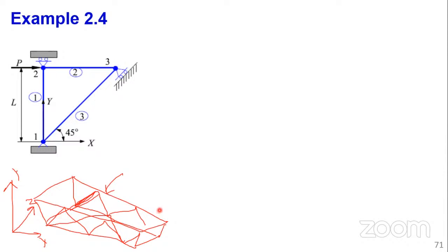It's just addition and reduction using the node boundary conditions. So if you don't define adequate boundary conditions, or if you over-constrain your structure and try to run your analysis, let's say in Abaqus, it throws an error, maybe telling you there are too many constraints. We are defining a boundary value problem, and the boundary conditions have to be well defined for our analysis to be tenable.